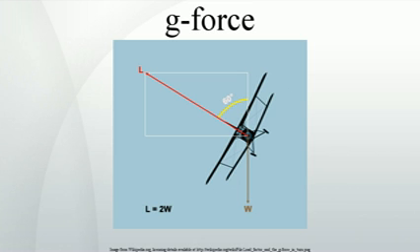Resistance to negative, or downward G, which drives blood to the head, is much lower. This limit is typically in the 2 to 3 G, about 20 meters per second squared to 30 meters per second squared, range. This condition is sometimes referred to as red out, where vision is literally reddened due to the blood-laden lower eyelid being pulled into the field of vision.